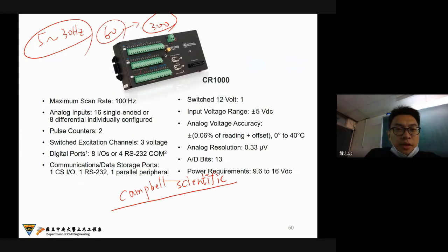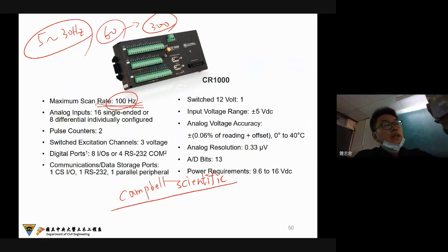But I would like to invite all of you, okay, guys. First, when you survey hardware, the first rate, this is the rate you need to be concerned with first, right? So this kind of data logger is maybe just for static behavior monitoring, not dynamic behavior. So this kind of data logger only has 100 hertz sampling frequency.